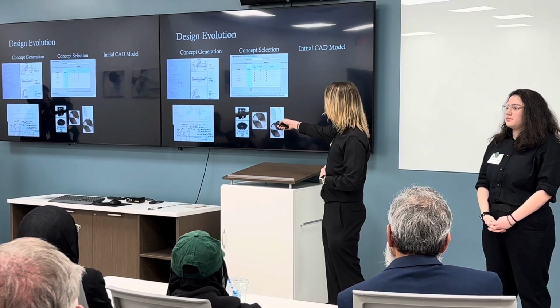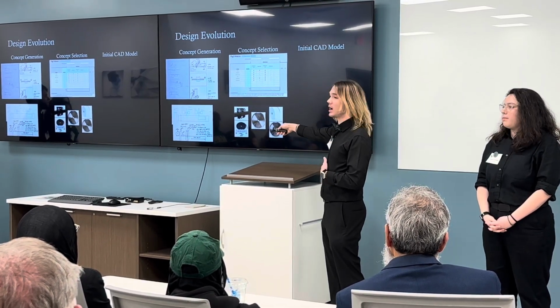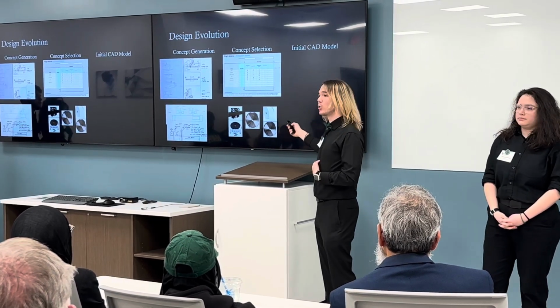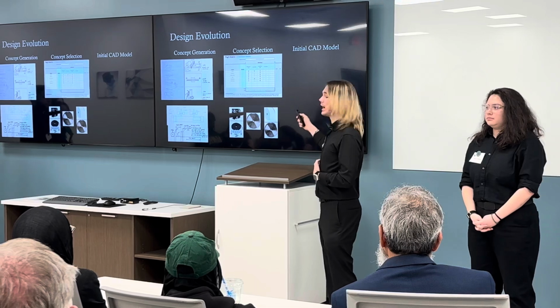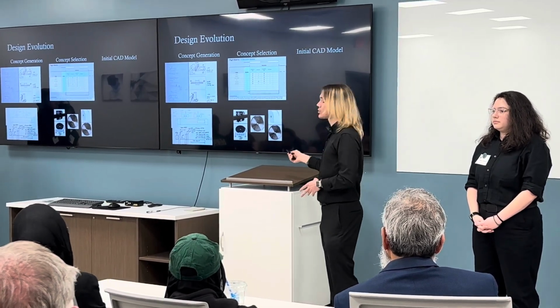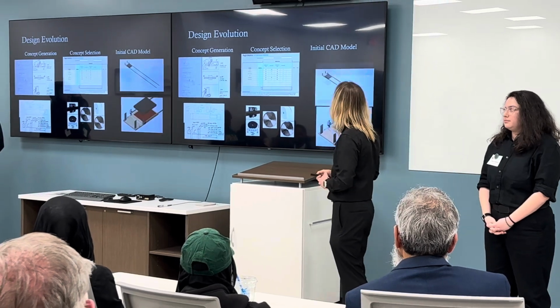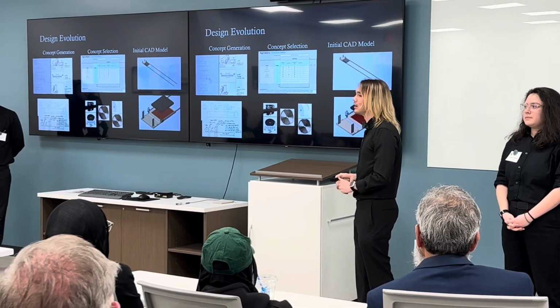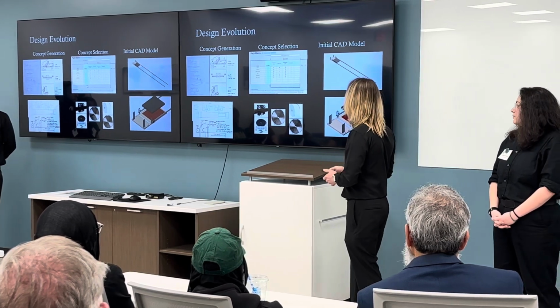And here for the motion system, we chose V-rollers and timing belts. For cutting, we are using a rotary blade. And then for the header press, we have a header spool provided by our sponsor, which will also be cut using a rotary blade. And then here's our initial CAD model. This was the first draft that we made of this before any optimization.